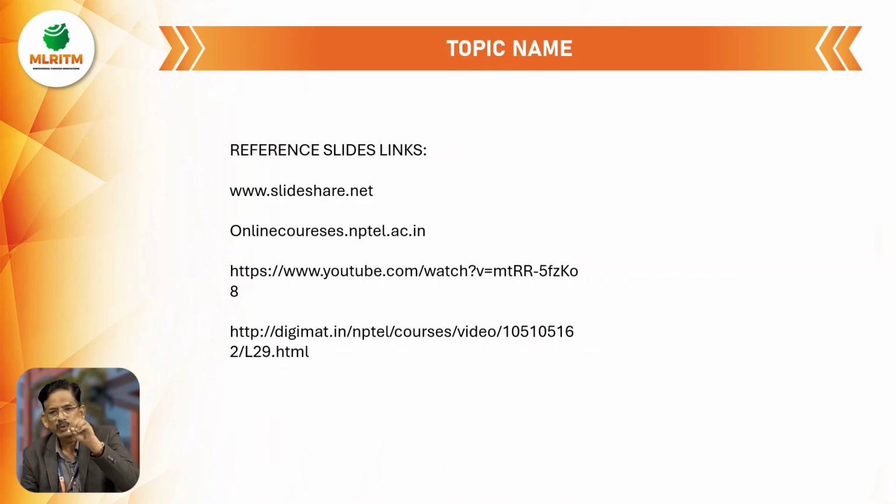So that's why you better take ISMB, medium beams. If it is less, you can go for ISLB. If it is more, you go for ISHB. So that's why you have to take the design like this. After that, you have to check the design bending strength, design shear force, and the deflection also. So these checks are necessary.